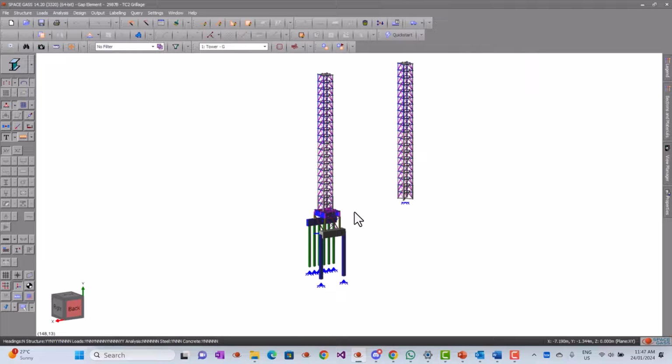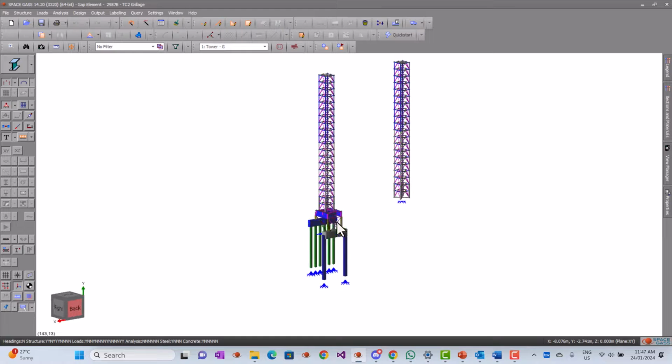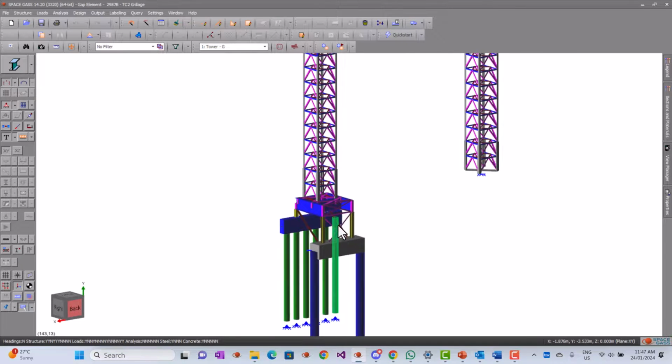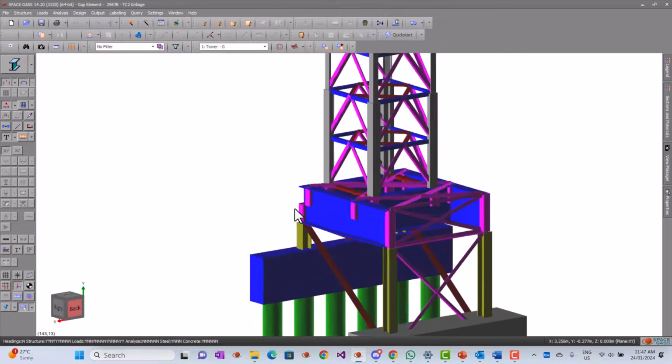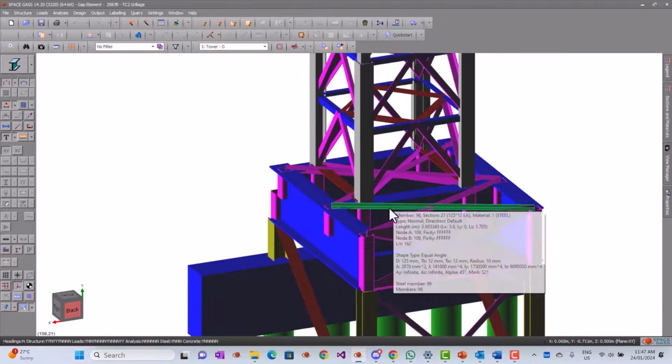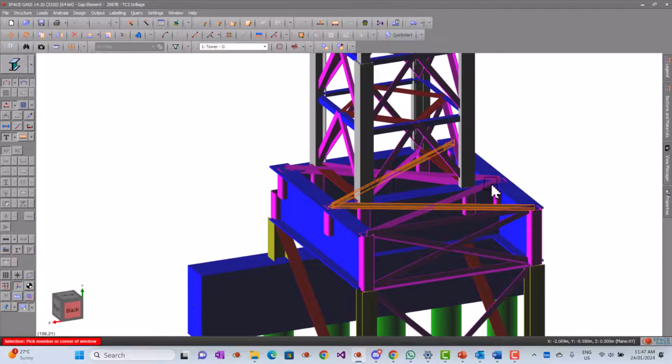When modeling braced steel frames, such as a crane grillage, it's common for bracing to become overstressed in the model due to minor deflections in the main beams. This issue is particularly prevalent in bracing the top and bottom flanges of deep beams, where the beam's flexure causes a slight axial displacement in the bracing member, leading to a significant axial load.